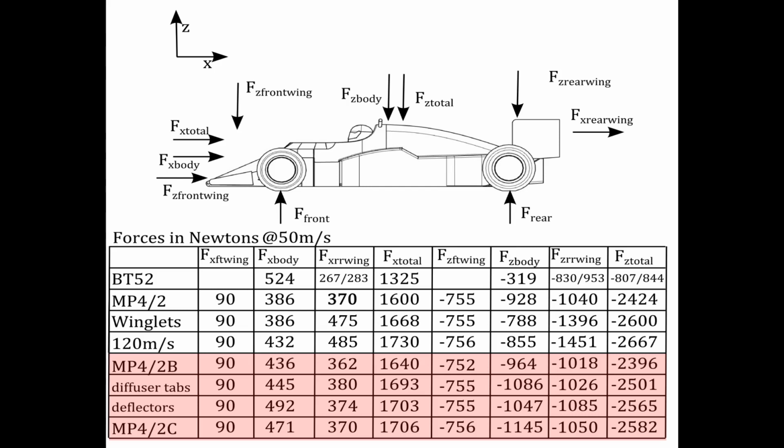Alone, the body was responsible for 122 newtons of negative lift, with 9 newtons of drag, basically all the additional downforce. Summing up the total from the aerodynamic components came to an increase of 33 newtons of lift and 26 of drag. Missing from the total is 28 newtons from the wheels in both lift and drag.